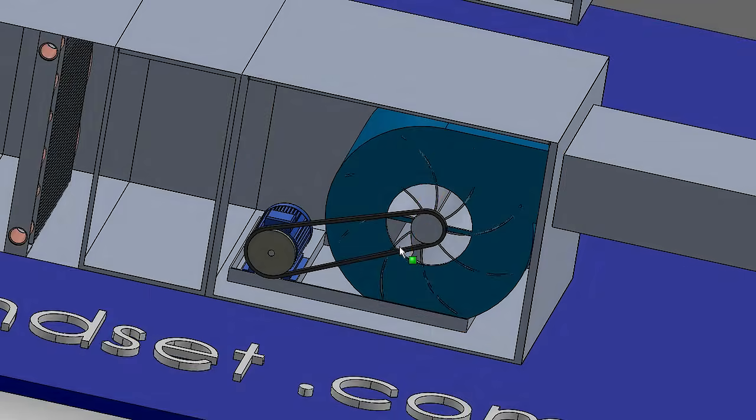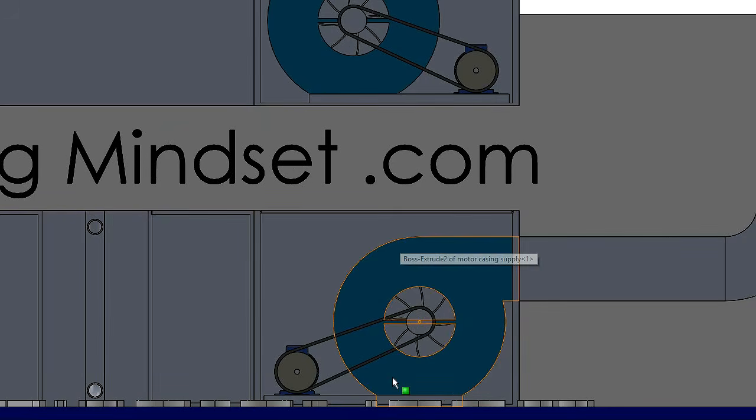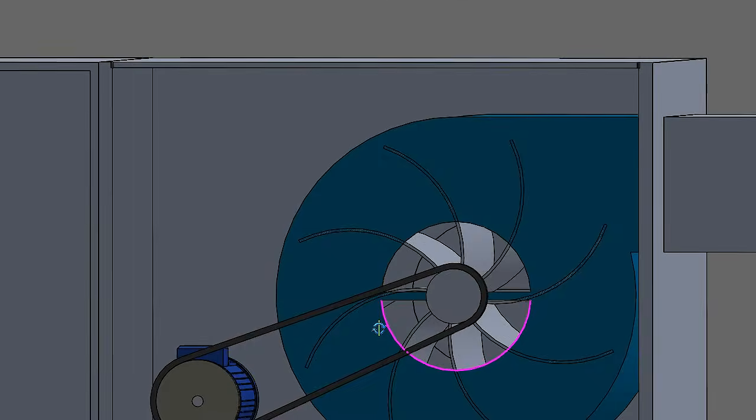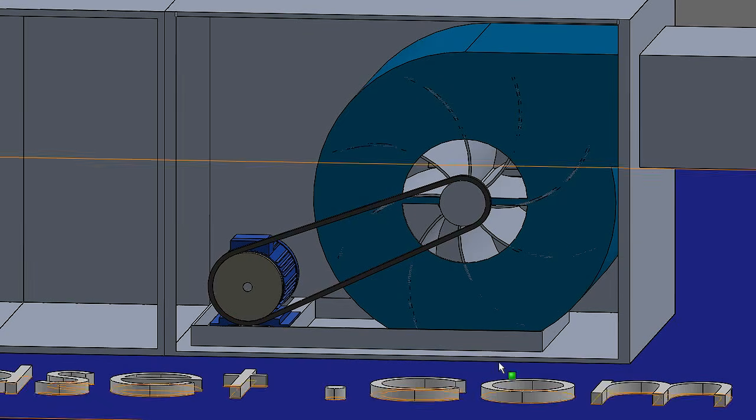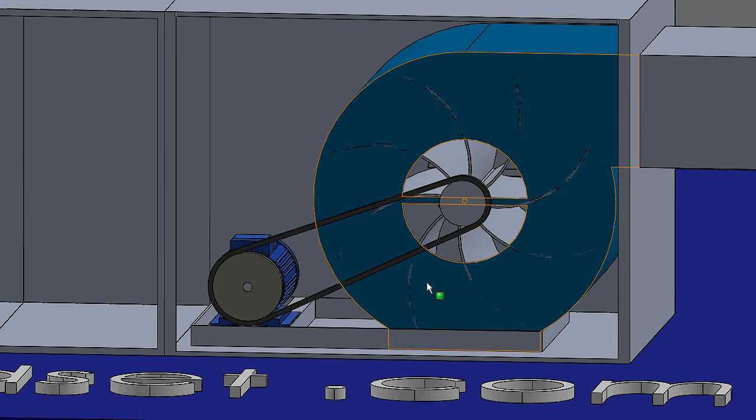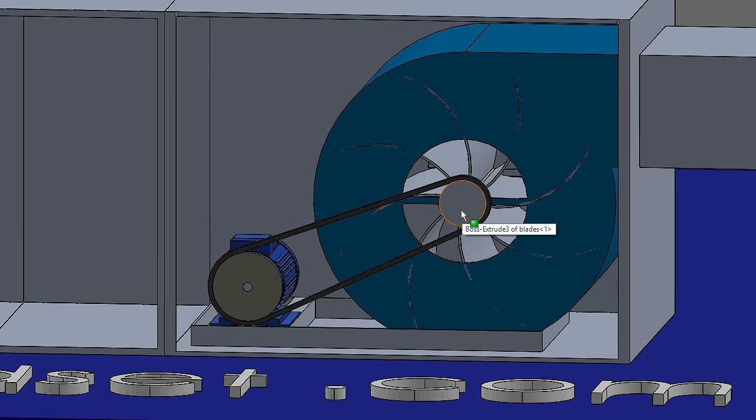And in fact, let's change that position just there a bit. There we go. No, let's rotate that a little bit. There we go. That's a bit better. So you can see here we've got an induction motor, and that's bolted down usually to a frame, because these are pre-built systems, and that's going off to the pulley, and then this is put onto a belt drive. And the end of the belt, this is kind of a rubber wire frame mesh belt, and that goes off to another pulley which is connected to the fan blades inside here.